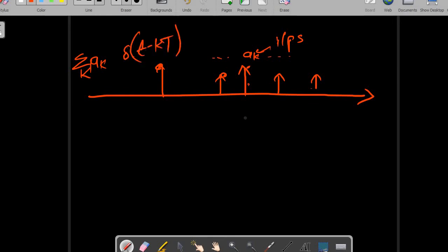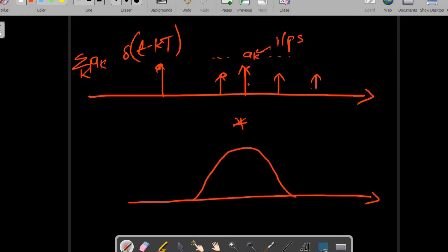Now when we pass through a filter, in time domain we convolve, so this is the convolution operation. Let's say, just assuming arbitrarily, the impulse response of our filter p(t) is given by this shape. It's more or less like a Gaussian curve.